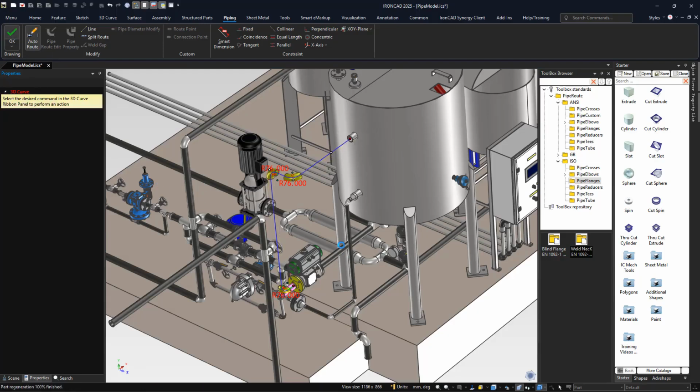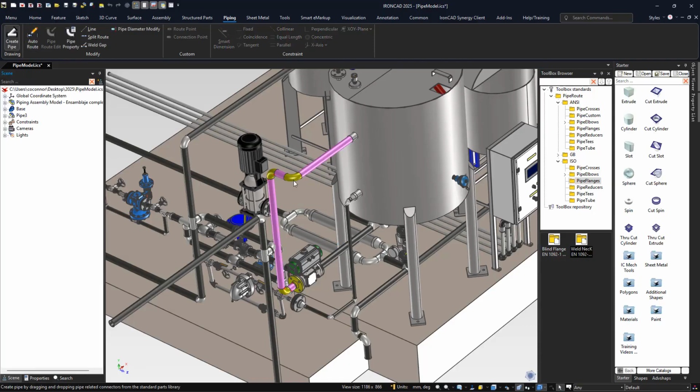And what it's going to do is swap out those bends, instead of using regular bends, and put our elbows on there, which are the yellow colored, and then the pipe runs. And you'll see in our tree, it actually creates this nice pipe run inside of here, which gives you the route information, the components that are being used inside of there. So you can see we've got 3 elbows and the weld neck flange, and then our route parts, which is just basically the pipes.